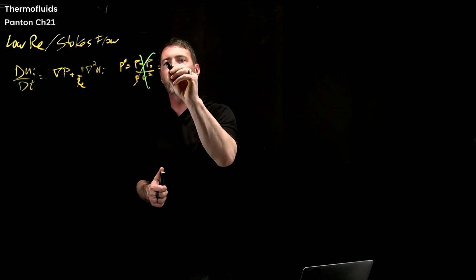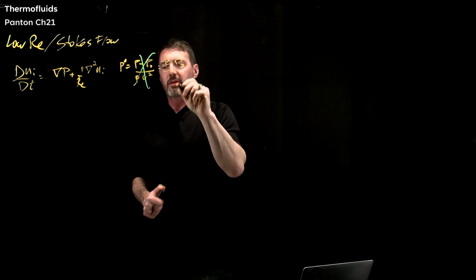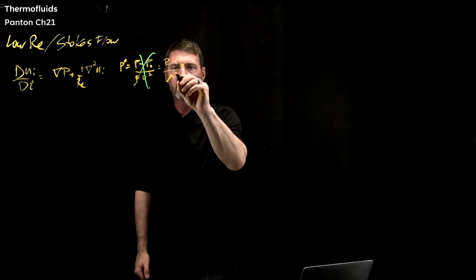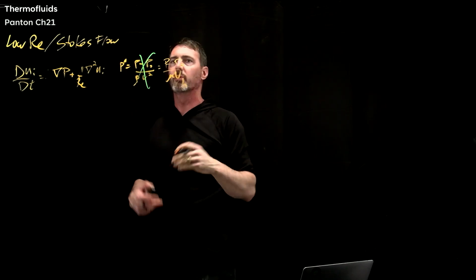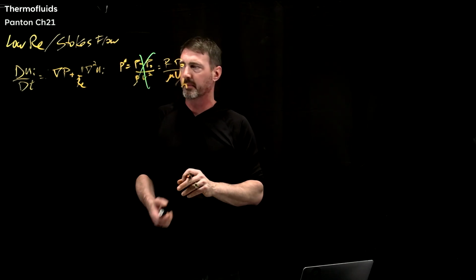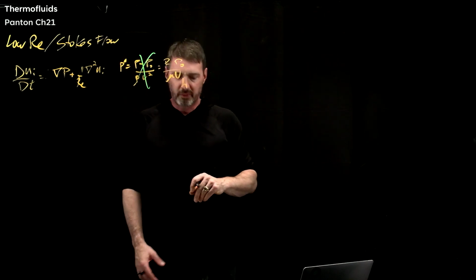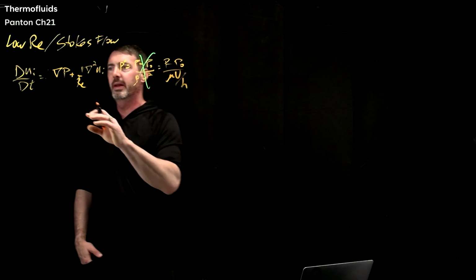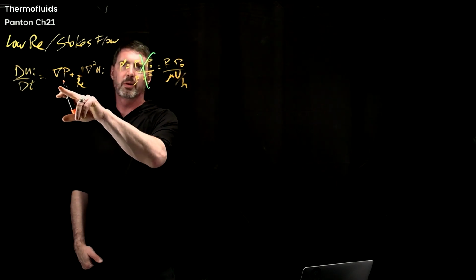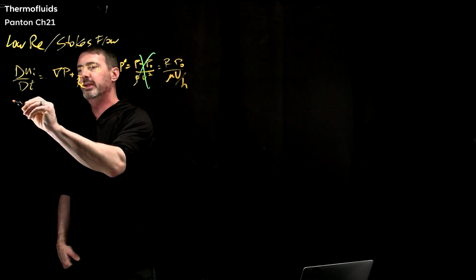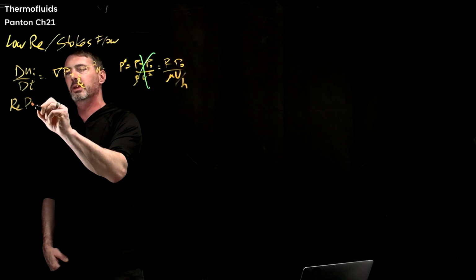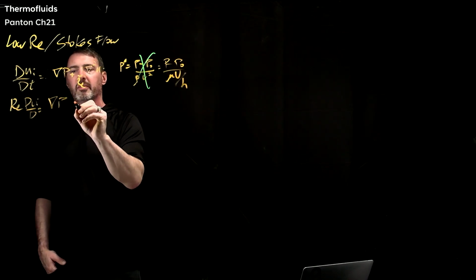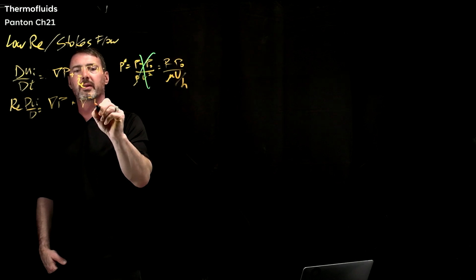And actually what you need to do is non-dimensionalize it versus viscosity. Okay, so mu times velocity over whatever your length scale is. Once you do that, this whole thing also picks up 1 over Reynolds number, and so you get Reynolds number times du_i/dt, all non-dimensionalized, equals minus grad pressure plus del squared u_i.